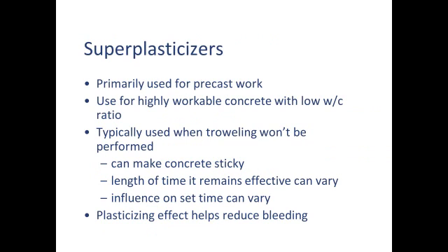So I'm going to be focusing on superplasticizers. They're the potent end of the spectrum of water reducers. Low range, very weak. You might add a couple inches of slump. Mid range is 3 to 5 inches of slump. Translate that to 75 to 125 millimeters of slump, let's say. And that's just a rough range. You could probably get it a little bit more. But your superplasticizers, that's where you're really getting 6, 8, 9 inches of slump. So 150 to 200 millimeters of slump.